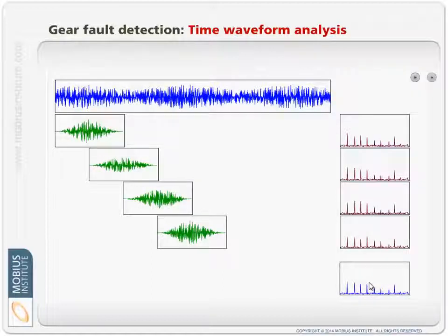So with normal vibration, this is just fine. There are limitations, and I've talked about those limitations in other webinars and certainly in our training and so on. But the fact is that for normal processes, that's an acceptable process. But when you've got more complicated vibration from a gearbox, all this windowing and averaging can really lose the information that we ultimately want to see.